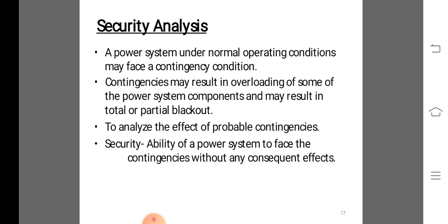Security control requires topological processing to build network models and uses large-scale AC network analysis to determine system conditions. Then the required applications are grouped as a network subsystem that typically includes the following functions. Come, let's go to the topology processor. It processes real-time status measurements to determine electrical connectivity, that means the bus model of the power system network.